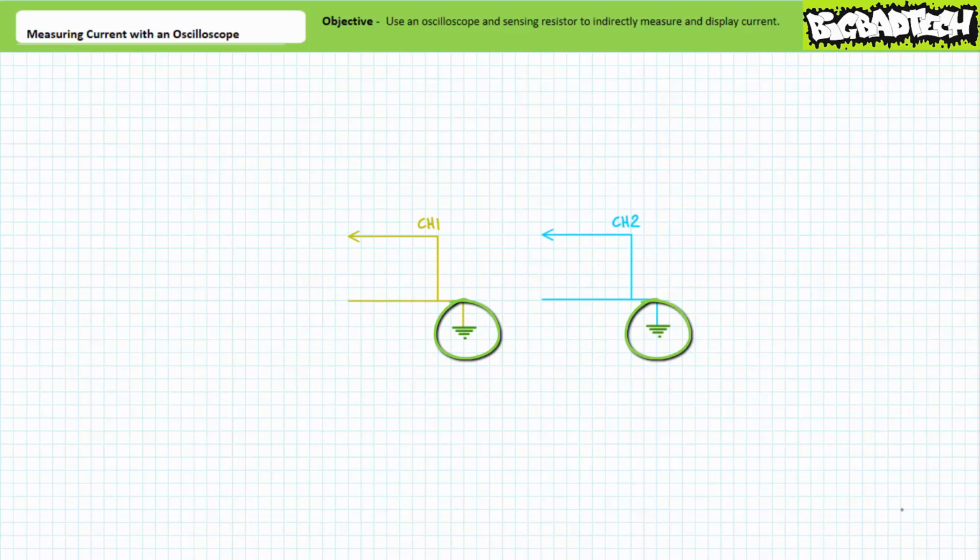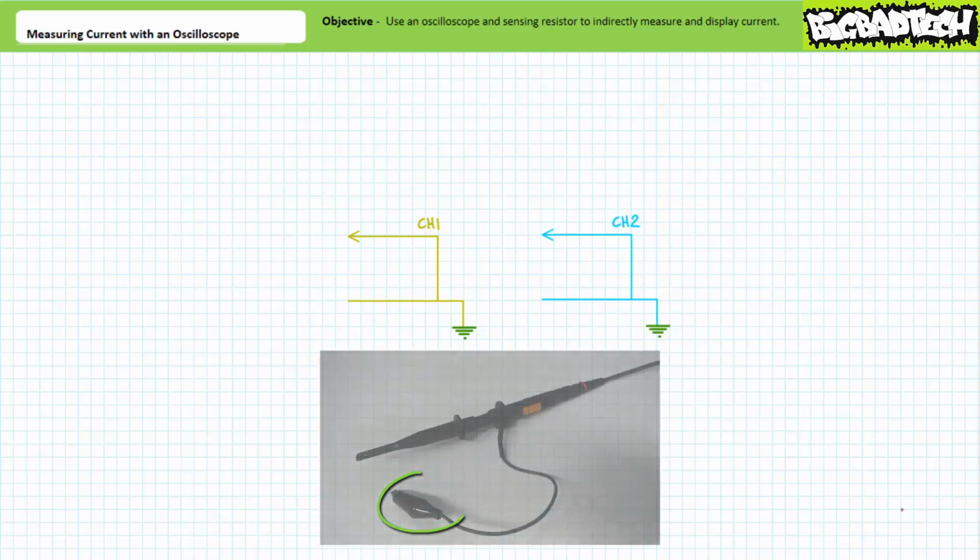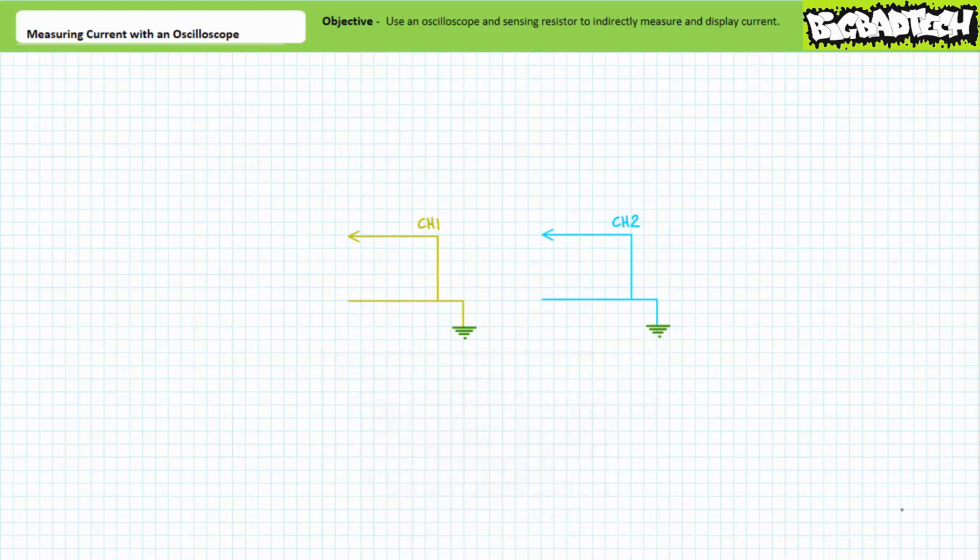This implies that the reference lead for both channels, ordinarily the small alligator clip dangling off the probe, is always hooked to ground. This isn't necessarily a deal breaker, however it does necessitate a user be aware of this fact and take the appropriate steps to avoid total disaster.